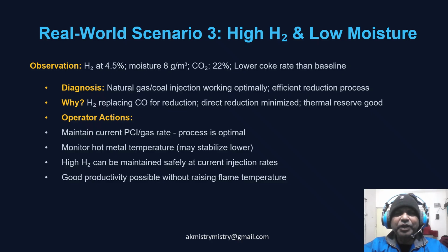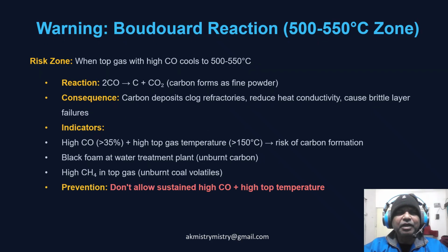Now, a warning about the Boudouard reaction in the 500 to 550 degree zone when top gas containing high carbon monoxide cools through this temperature range. The reaction 2CO forming carbon plus CO2 can deposit fine carbon. This carbon can clog refractory, reduce heat conductivity and create brittle layers that fall